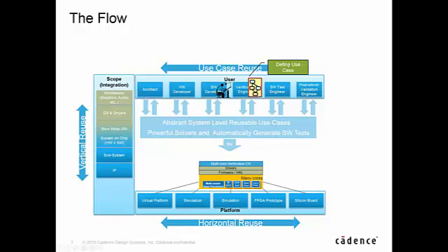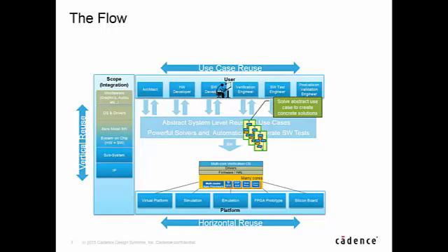Okay, you start with the user defining their use case, and that use case is captured in an abstract form. So it's done by capturing the actions and resources of your SOC. And so it is done at an abstract level, so the modeling is not too onerous, yet it's sufficient to allow for us to apply some formal solver technologies to it. Now what happens is we take that abstract use case and the solver gets applied and it comes up with a set of concrete solutions that would fulfill that use case. And I'll show some more about what that looks like in real life in some subsequent slides here.